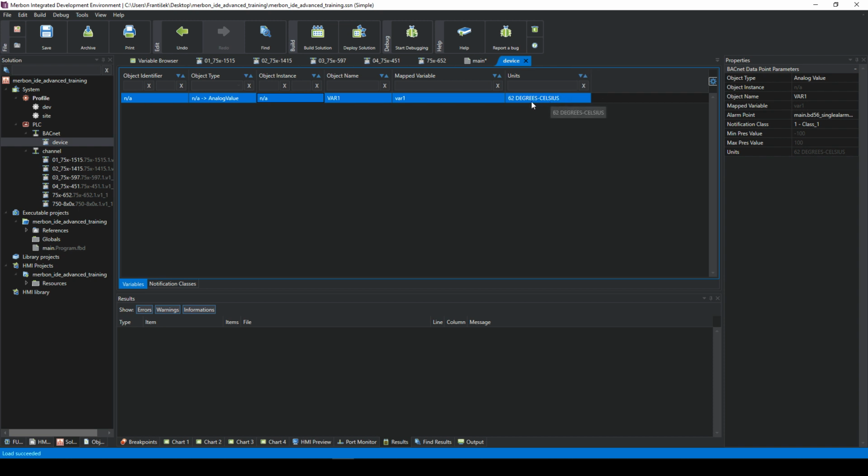You see, about the units, there is one thing in BACnet communication. BACnet itself has its own type of units. They have numbers, but if you write the value in a normal way, it will automatically add the BACnet type of the unit, so the clients can read your variable in the right type.